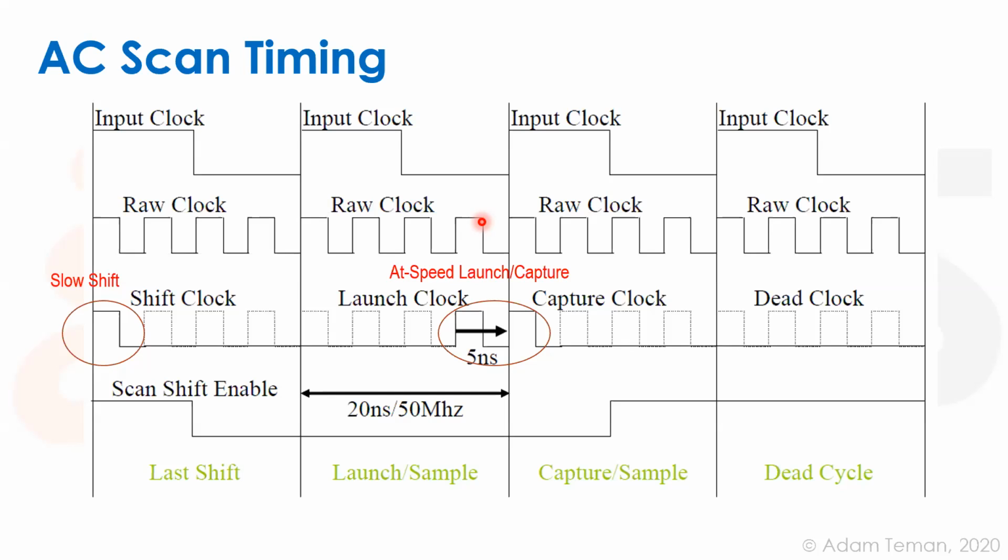Yeah, it's definitely done, and there's usually a big struggle to clean it when the chip comes back. The cleaning, I can tell you from my experience, we had Tsachi maybe remembers it. It took more than 2 years after our silicon came back from manufacturing to approve the test program. Just to figure out why this test is failing, and then you give up and you say, okay, remove this test from the suite, and then you need to justify it and do failure analysis, and it goes on forever till you give up.